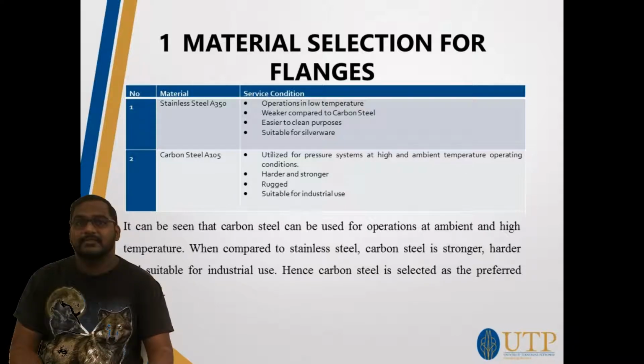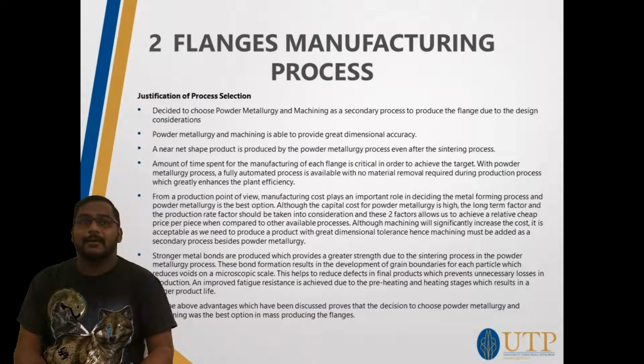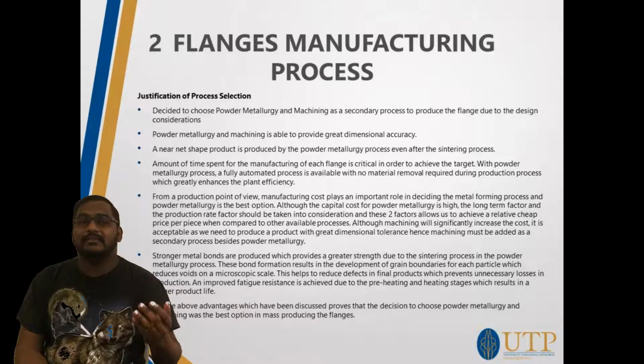to manufacture the flanges. To manufacture a flange, there are actually many metal processing techniques. The ones we researched were casting, forging, powder metallurgy, and machining. We categorized them to choose the best processing technique. Besides the description of the process, we also talked about dimensional accuracy, the operation time, the mass production cost, and the advantages and disadvantages,